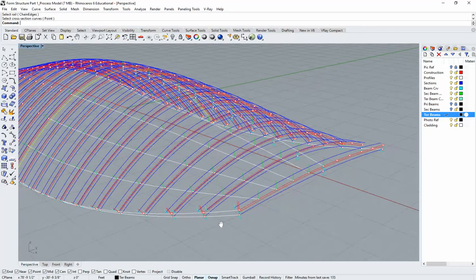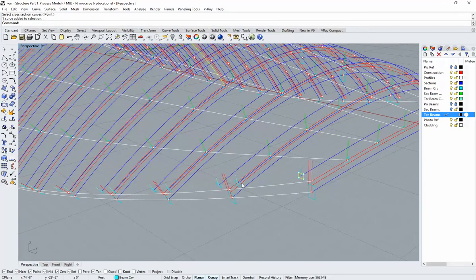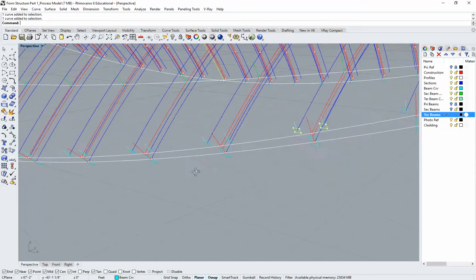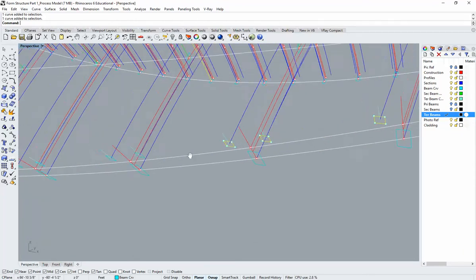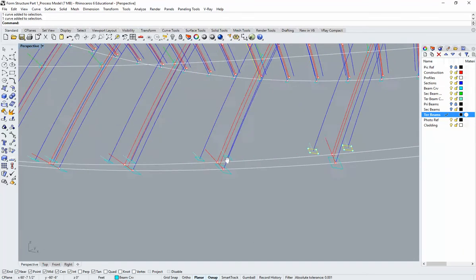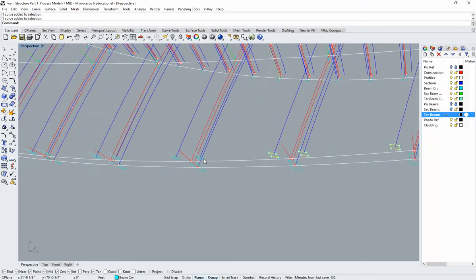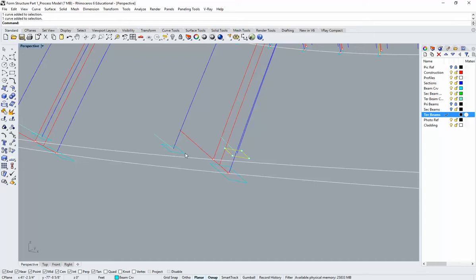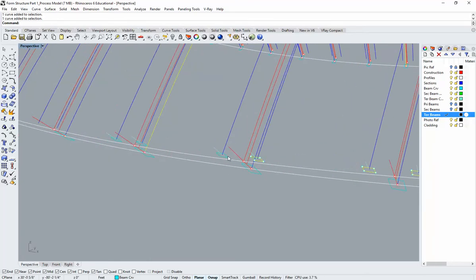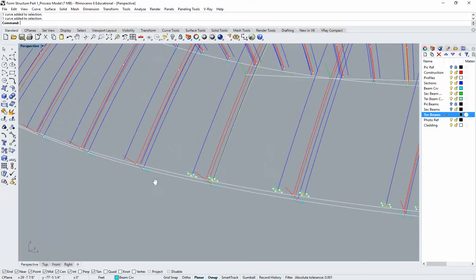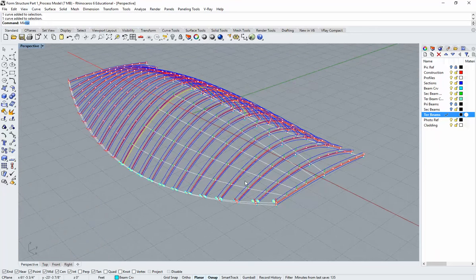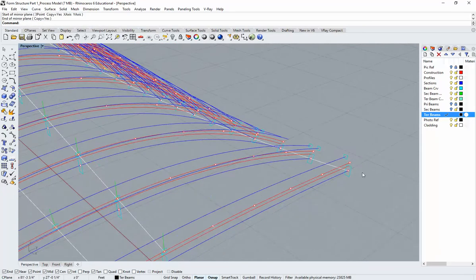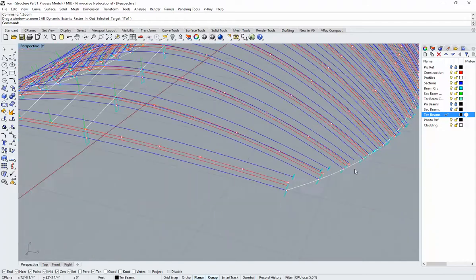Oh, just before I do that, sorry. All I need to do, and this is simple to make everything really nice, is to just copy and mirror all those profiles that you just drew. All those section curves to the other side, so we could mirror this thing around. Yeah, like this. All right. Mirror that from wherever over here. So now they're on the other side as well, because that'll make a better, cleaner sweep.